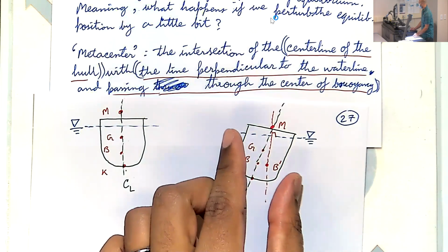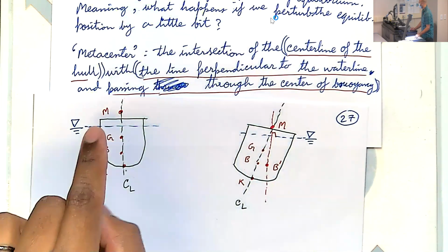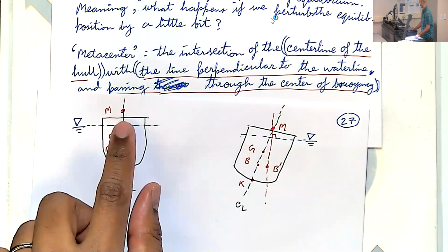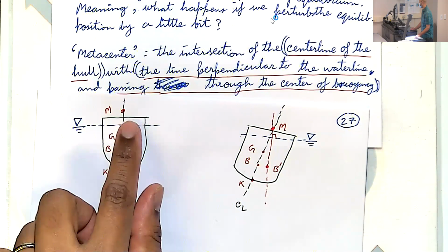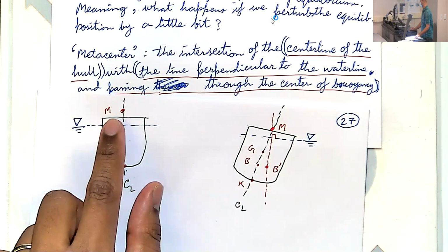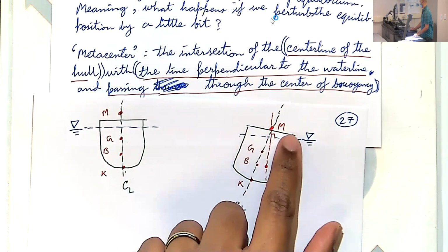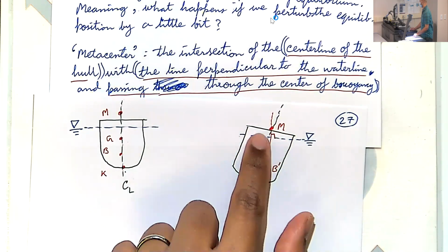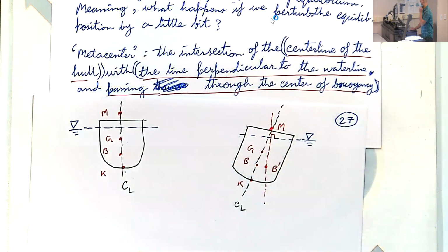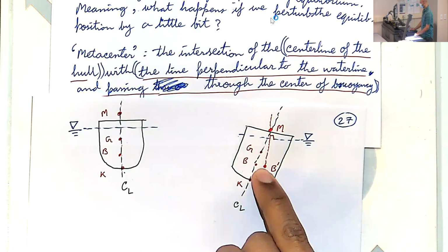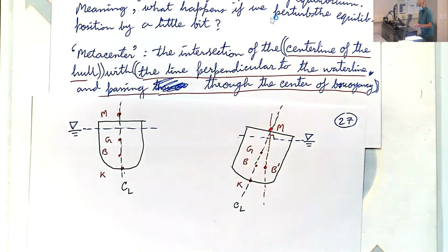So when we tilt the hull, see here, the dry volume on the left half was some value, and now it's slightly larger. And the opposite happens on the other side. Now you've submerged some of the dry volume. So the center of buoyancy naturally moves a bit to the right side. And we'll figure out how much it moves.